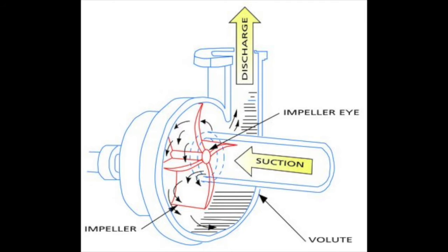When considering pumps, the most common radial flow pump is a centrifugal pump, which has two main components, being an impeller and a stationary casing enclosing the impeller. Contrary to a turbine, work is done on the fluid by the rotating blades, creating a large increase in kinetic energy and an increase in the pressure of the fluid flowing through the impeller.